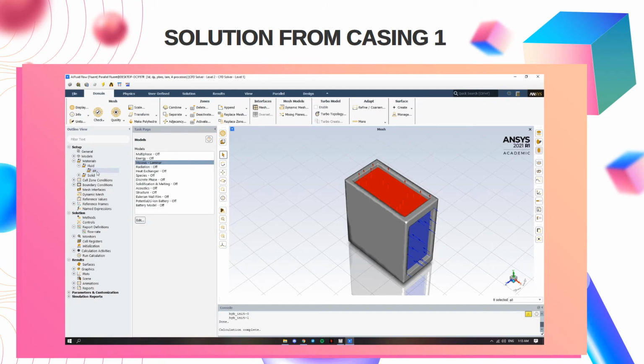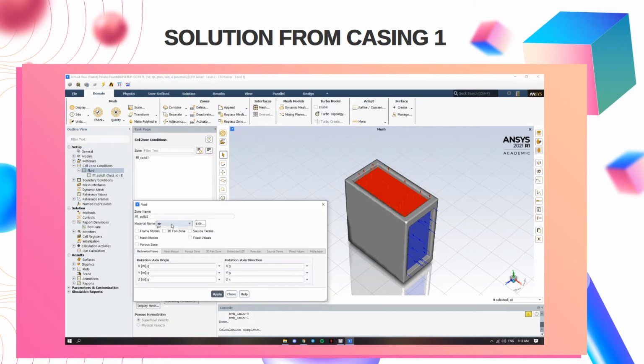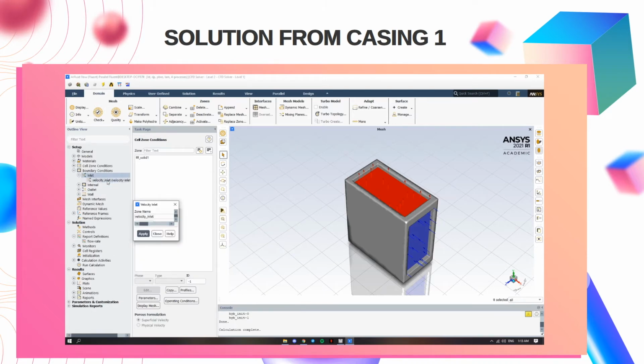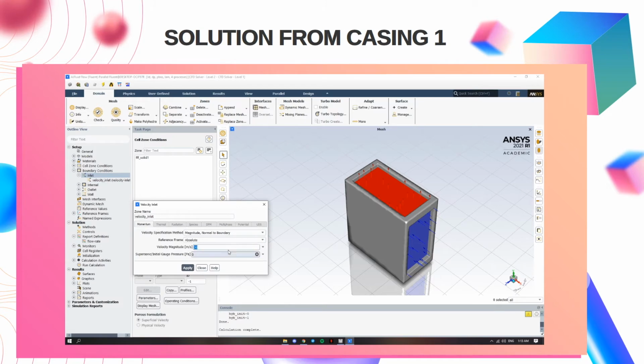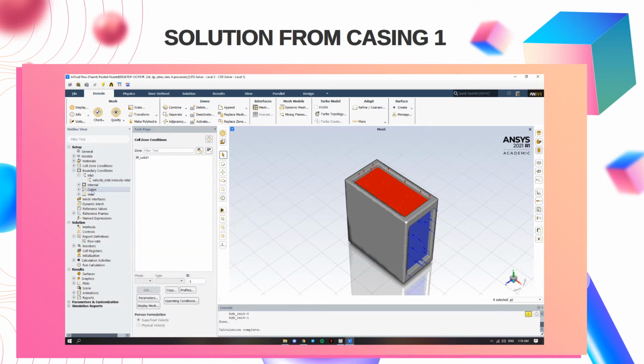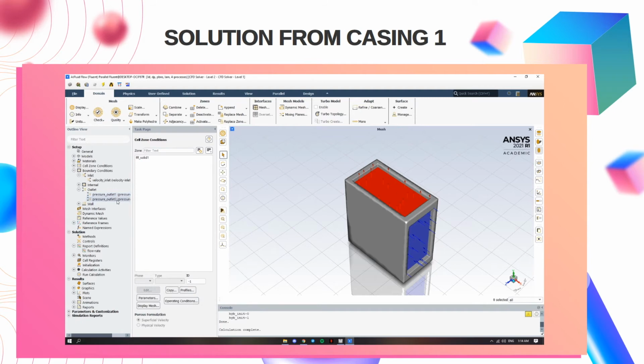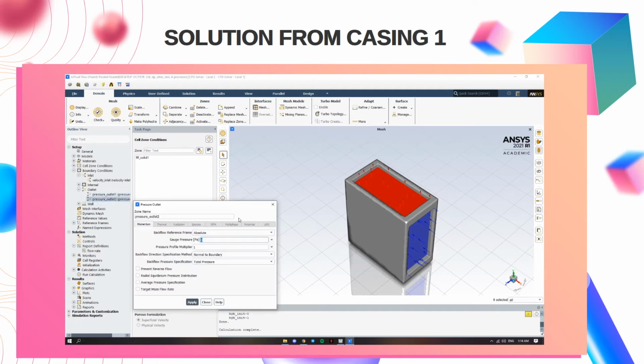We use air as the medium, and the solid we use aluminium. So the cell zone condition we use also air as the medium. Okay, boundary condition, we have inlet and outlet. From the inlet we use 30 meters per second for velocity magnitude, and for the first outlet we use 0, and the second outlet also we use 0 as pressure.